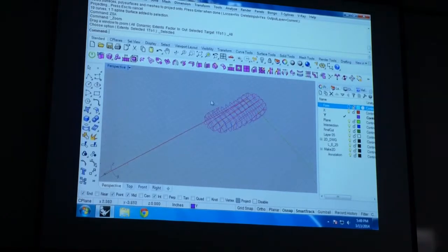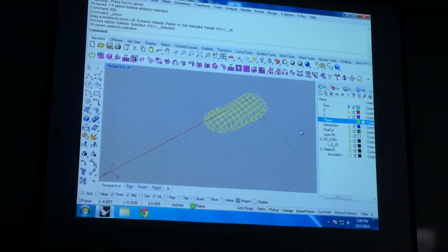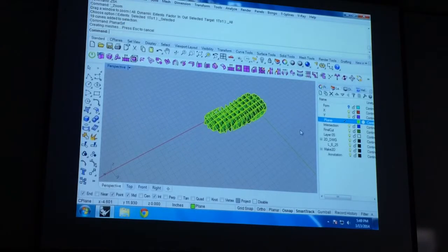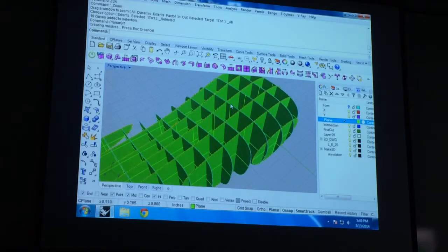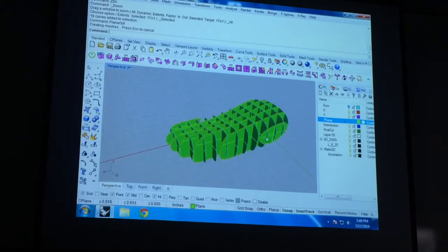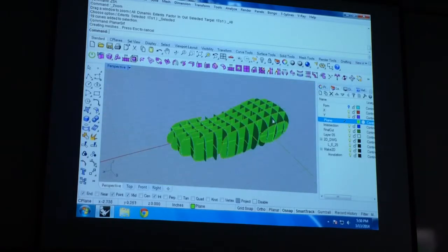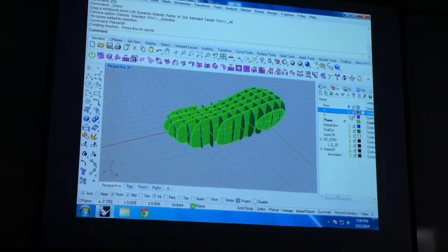Okay. So select all of the lines and activate plane layer and planar surf. Planar surf. It's a command. Okay. Now we're gonna run the intersection command to get the middle line. But at this point, if you have X and Y layer turned on, it will try to intersect between all of these points, and that's going to create a lot of lines. So make sure you turn off X and Y layer.